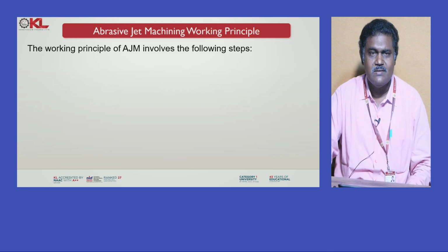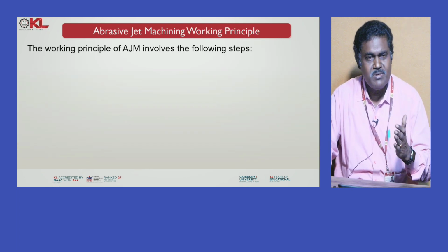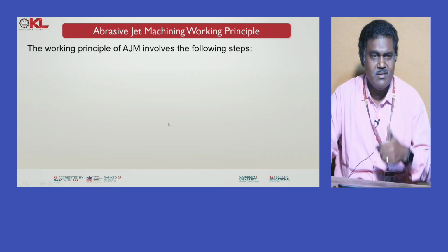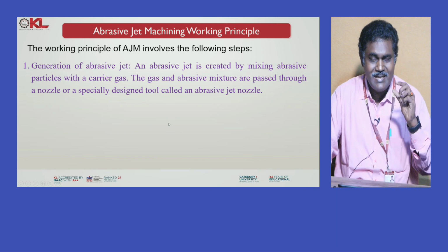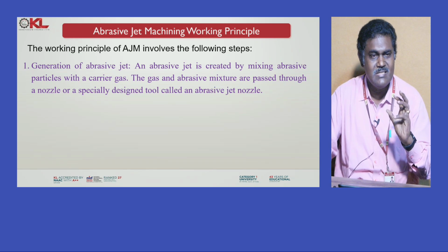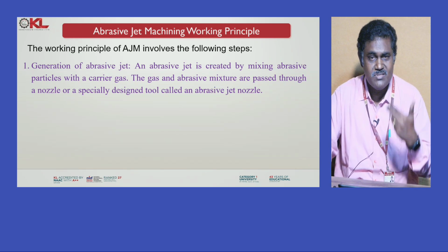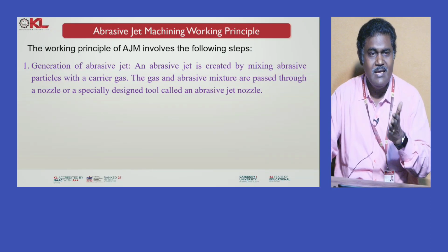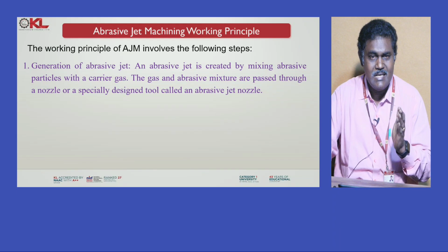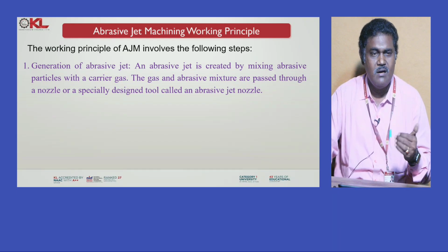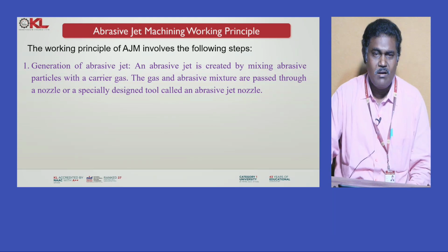Now let us see the abrasive jet machining working principle. The working principle involves the following steps. One is generation of the abrasive jet. Just now we watched the setup and how we can generate the abrasive jet. The abrasive jet is created by mixing abrasive particles with a carrier gas. The gas and abrasive mixture are passed through a nozzle or a specially designed tool called an abrasive jet nozzle.